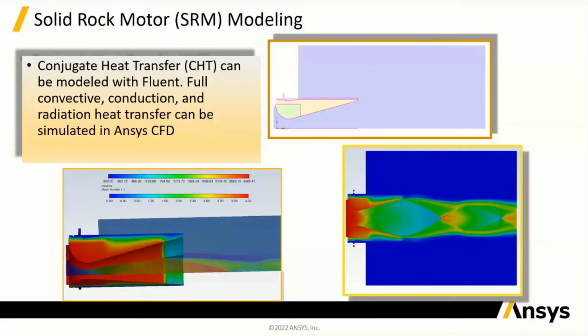Next step is to put the ablation onto this. It works very well static. I've started testing now with doing the moving and deformation of both the fluid mesh and the solid mesh at the interface, and being able to change the meshes on both sides to take into effect the recession rates and the deformation going on in the process. Hopefully this will be ready in the pre-release coming in the next year.